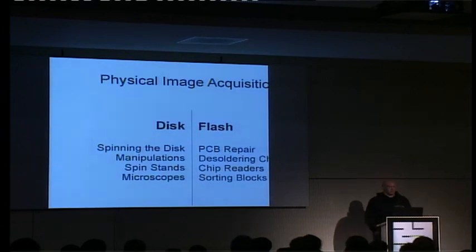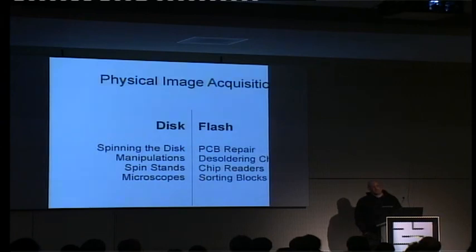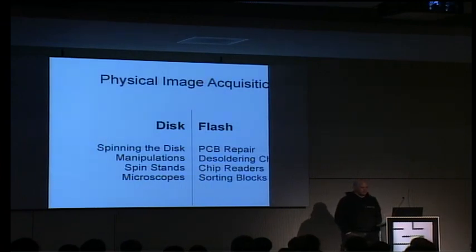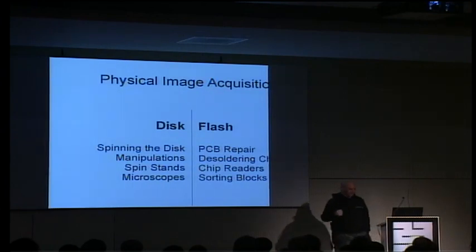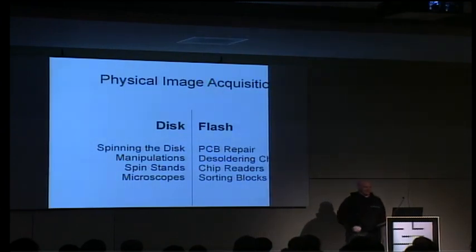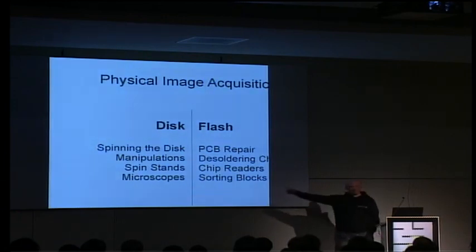And the last resort actually is the MFM, the magnetic force microscope, that can take images from a piece of a platter as small as, let's say, 10 microns square. So if you are using the hammer and destroying all the platters, that will not be good enough against the microscope approach.